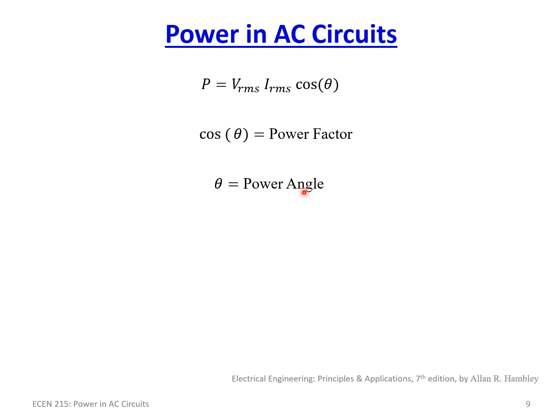So in some of the homework or on the test, you're going to see things like, given this circuit with a power factor of, say, 0.7 or a power angle of 25 degrees, given VRMS and IRMS, what is the power? You should be able to solve that because if you're given a power angle, you would plug the theta in here, get the cosine of that, say 25 degrees, and multiply it by your RMS values.